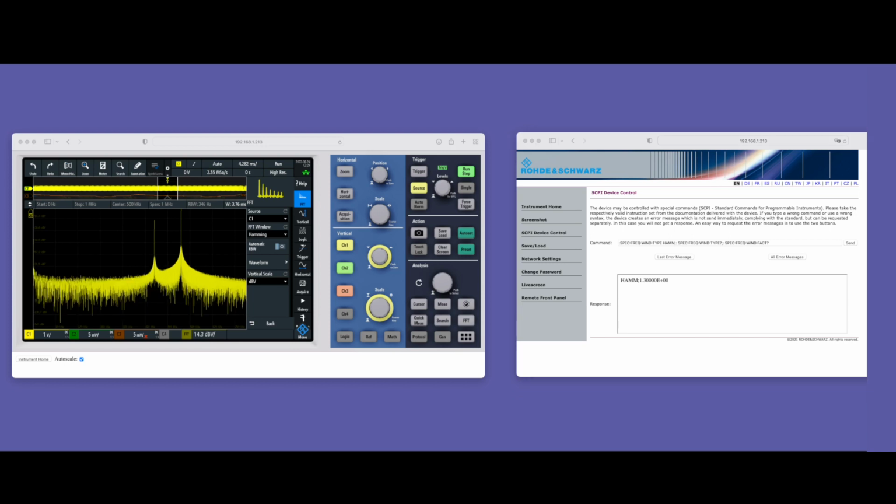I will now bring it back to the flat top, what I had before, and we see back here in the web interface it's on flat top. I'm choosing flat top for my experiments here because it has the largest factor, 3.84, so it's easier to work through the formula and really see the proper setting. That's the only reason I'm choosing it right now, not because of particular properties, but just because of the FFT formula that I would like to explore.